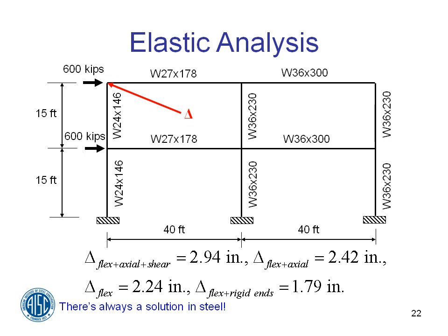But of course we do have deformation in that panel zone. And so the analysis for steel should be going from node to node or center line to center line without using the rigid end offsets. Okay? If that didn't answer your question, type it back in again and we'll see where we go. Thank you, Lou.